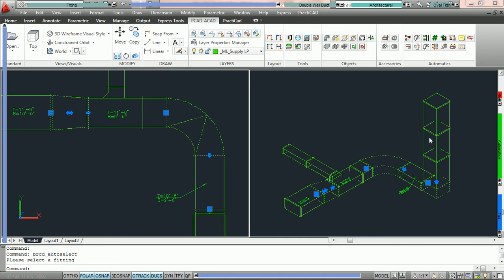Here you'll see that the rectangular duct was not highlighted. There are no top bottom changes for the rectangular duct. And most importantly, the fitting itself starts in a different elevation as opposed to the elbow here, which comes at one elevation and finishes off at another. So there's a slight difference between those two options. Most of the time you can choose either one and it would work just fine. So that'll conclude the selection tab parameters.